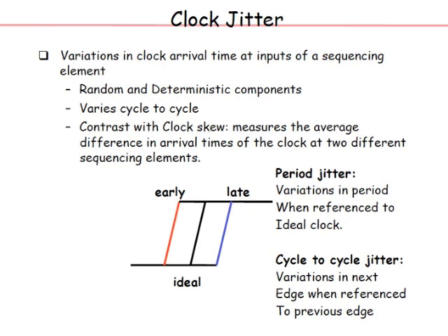is periodic, right? So you take every period and, when you draw the graph, you just overlay it on itself. Imagine that the next period edge also lies on the same one. So you get an overlay diagram, right? That's what you get when you look at this on an oscilloscope. Imagine that you have an ideal clock. You trigger the oscilloscope and look at the actual clock. If the actual clock had exactly the same period all the time, you'll just get a straight line like this on the oscilloscope.